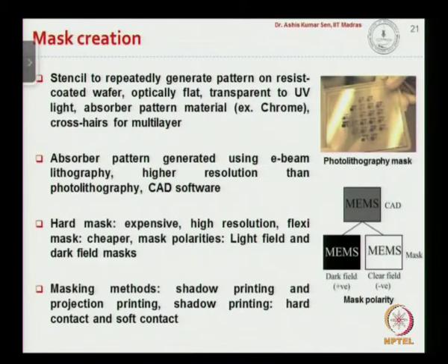Now, let us look at the first step of fabrication, which is called mask creation. Typically a mask looks like this. This is a photolithography mask. It will have a pattern depending on the structure that you want to create. The patterned areas, all those black areas that you see here, are opaque to light, so they do not allow light through in those areas of the mask.